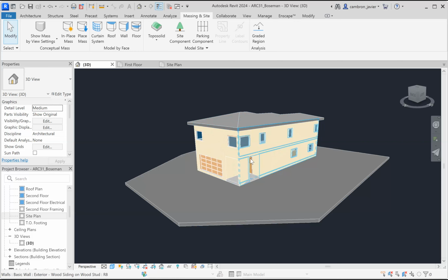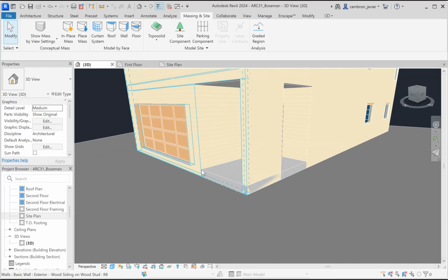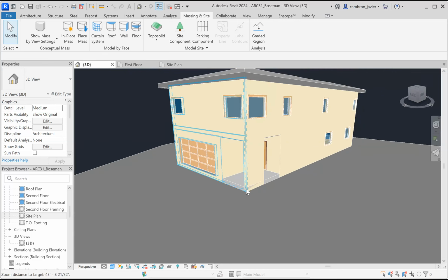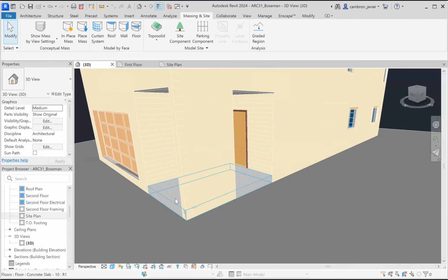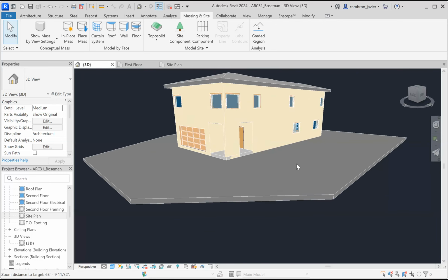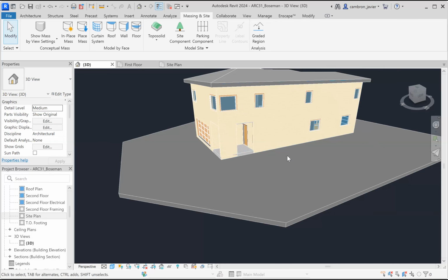Now, the other thing that we need to keep in mind when it comes to topography is that when we're building a house, the ground is never at the same height as your finished floor. Remember that when it rains, we always want to divert water away from the building. So in order to do that, we create the landscape 6 inches from the finished floor. This way the house is always 6 inches above the grass or the dirt, so it will never get flooded, or the idea is that the water will never actually get inside.